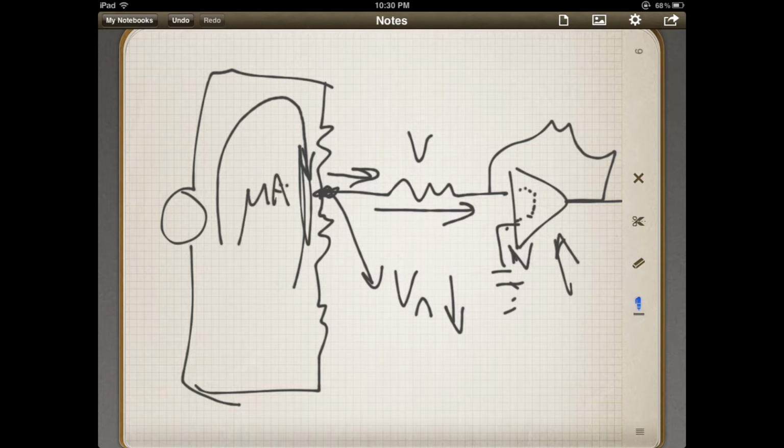You definitely want an op amp that is either in nanoamps, or if it has to be in microamps, you make sure that this is maybe like 100 microamps, and the leakage of this guy, or its input impedance, and the current that will be sunk by the input is like a microamp, or maybe 5 microamps or something. That way you've got a huge gap.